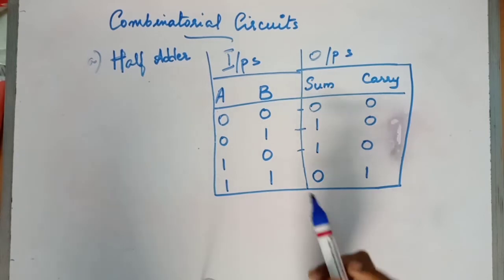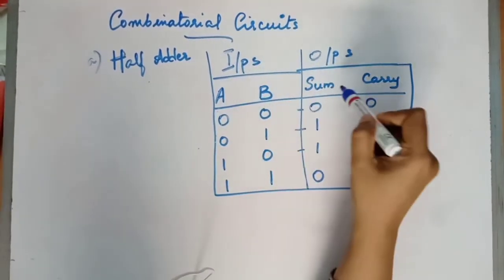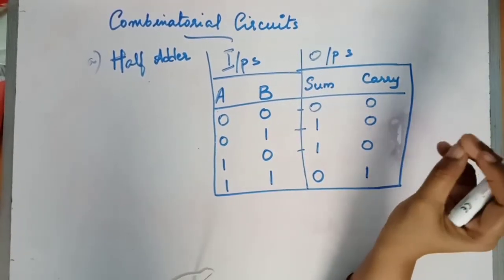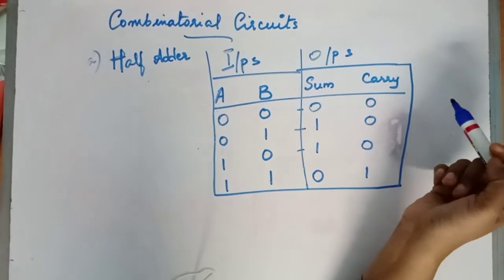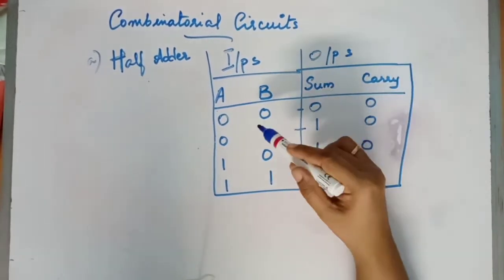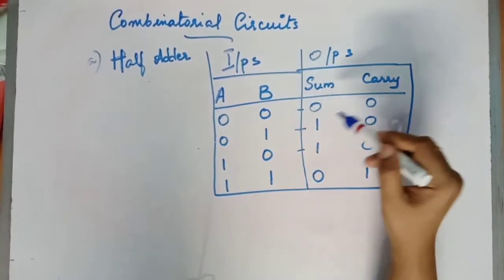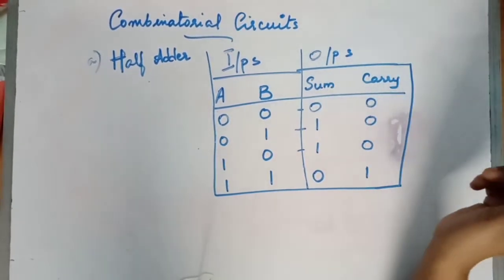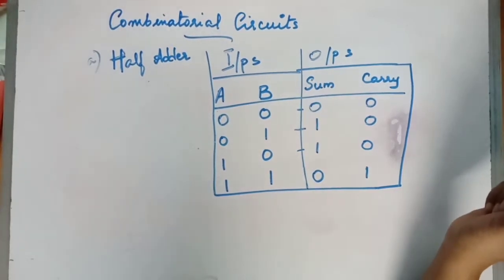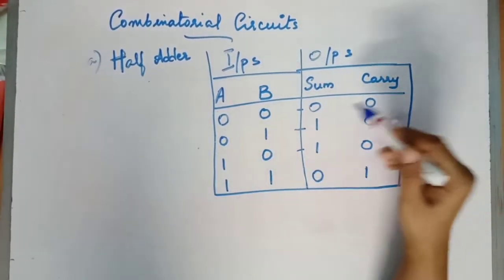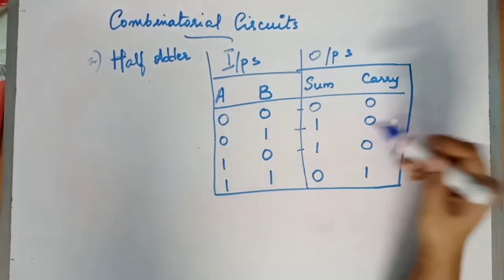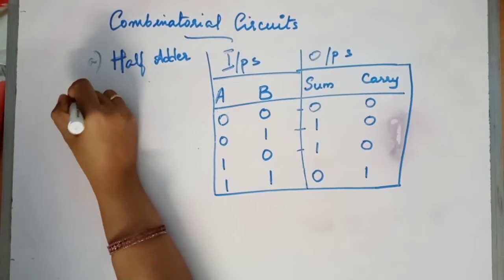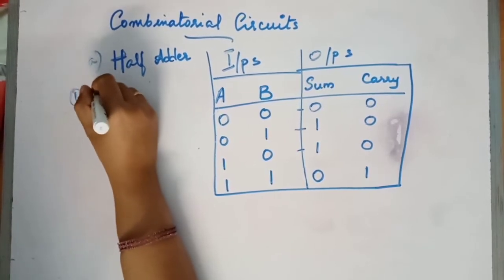First of all, we know how many inputs are there, how many outputs are there. Based on the number of inputs, if you have n inputs, you'll write the 2 raised to n input combinations, and after that, for each set of inputs, you'll write the outputs based on the nature of the circuit, whatever application you need. First you will write the truth table.